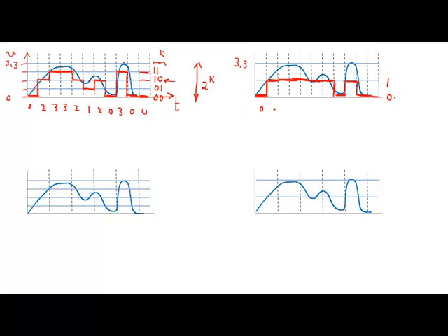Here you're going to read 0, 1, 1, 1, 1, 1, 1, 0, 1, 0, 0. Now, here on the bottom figure, the number of levels that I have is the same as the figure above it. So here again you have the values 0, 1, 2, 3. Here you have the values of 0, 1. But now the sampling time is one sample every 2 microseconds, right?